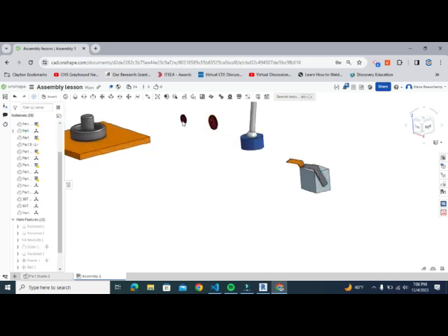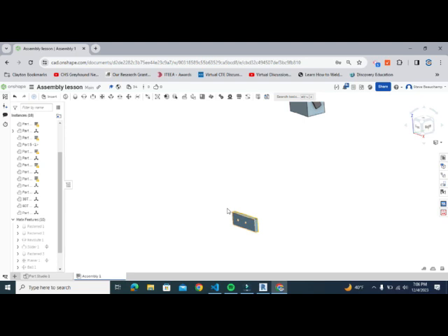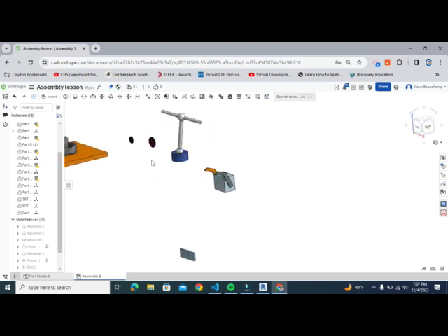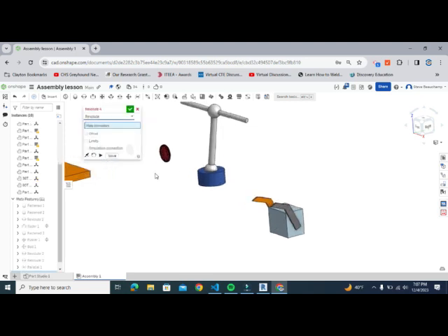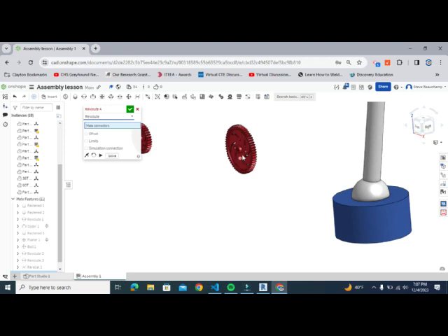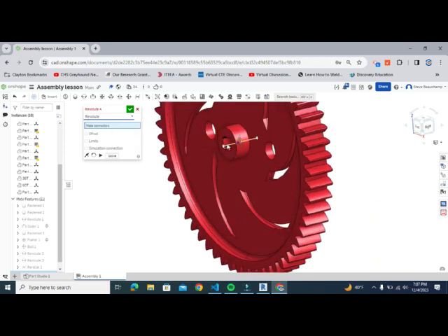So what I'm going to do now is I want to put this gear and this gear in these holes. Okay, so we're going to use revolutes for that. So we're going to go ahead and click M on the keyboard. We're going to change this to a revolute. And then it doesn't really matter which gear we're going to start with here, but let's say I choose this one. So this gear actually has a square hole, so I can either hover over the surface, hold shift, and then get the middle,